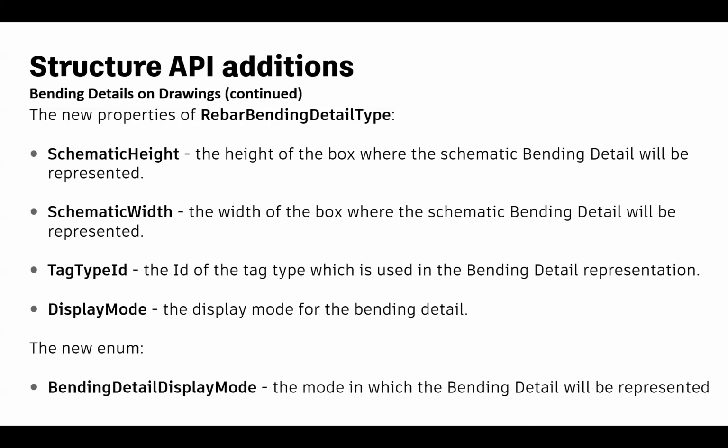There are also new properties of RebarBendingDetailType: SchematicHeight, SchematicWidth, TagTypeId, DisplayMode, and the new enum BendingDetailDisplayMode.